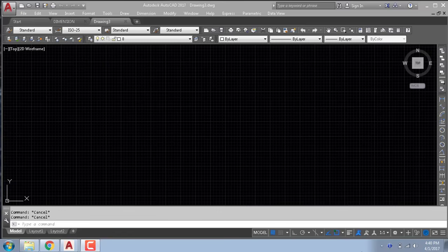Then how to set up all these? First thing is unit, second thing is styles, arrows, and what is the text style. So it differs in other drawings. Sometimes it happens when you are making one drawing and your text is not visible. In that case, you need to know the basics of dimension styles so you can configure it yourself.